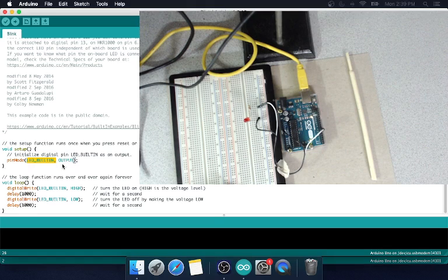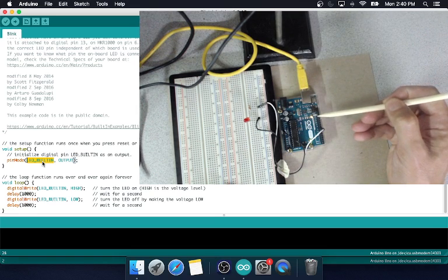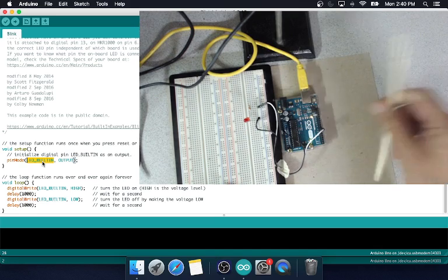And they're setting that to an output, which, if you think about it, makes sense. The Arduino is sending something out to a component. It's not reading something in from a component. So we initialize that and set that. And little known fact, LED_BUILTIN is actually assigned to pin 13, and pin 13 is right here, actually right across from the LED.